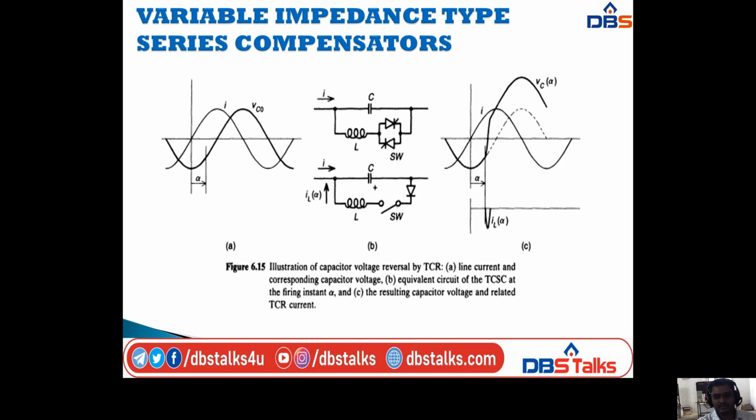In the B diagram we have two arrangements. In the first arrangement we are taking the TCSC, and in the second we are taking the equivalent circuit of the TCSC at the firing instant alpha. Here I am taking diode and switch and inductor and capacitor like that.